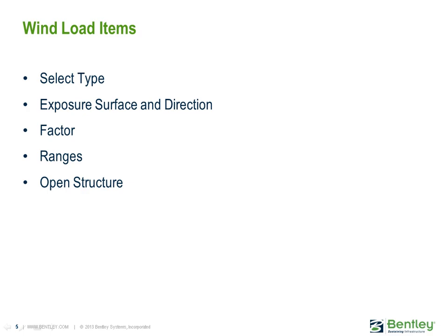After the wind load cases are created, you can now add wind load items to those load cases. The wind load items will use your wind load definitions, and by entering the different parameters such as the type or the exposure or the factor to those wind definitions, you can instruct STAAD.Pro on how to apply the wind load to the model. In addition, we also do have a toggle to define this as an open structure.